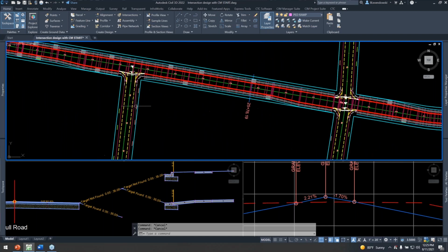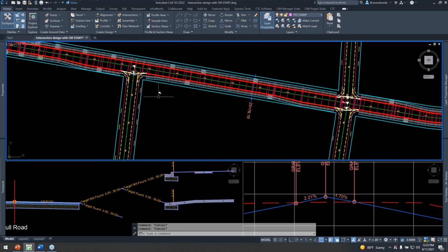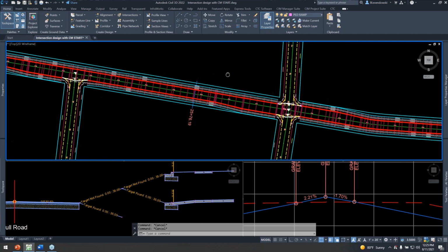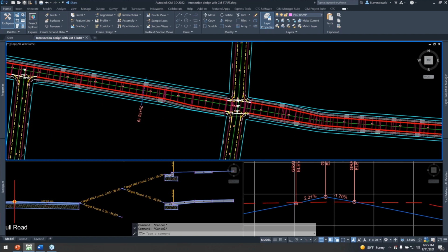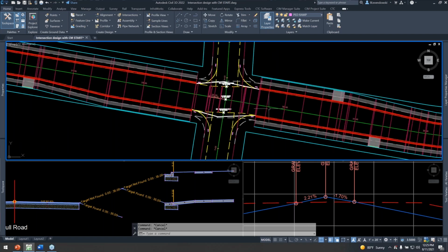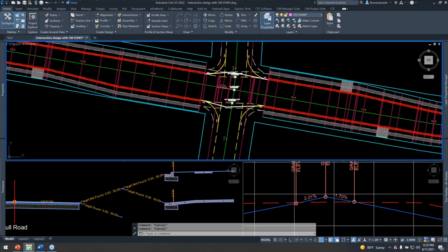All right, let's move along here. Let's build out, I'm going to do it fairly quickly, the side roads, the through road portions of them, and then we'll focus on those intersections. But it's key, I wanted to show you how I do it from start to finish with Corridor Mapper. And while we're focused on intersections here, the key point I want to make is model your through roads first, so you start to get the area that you need to model with intersections.